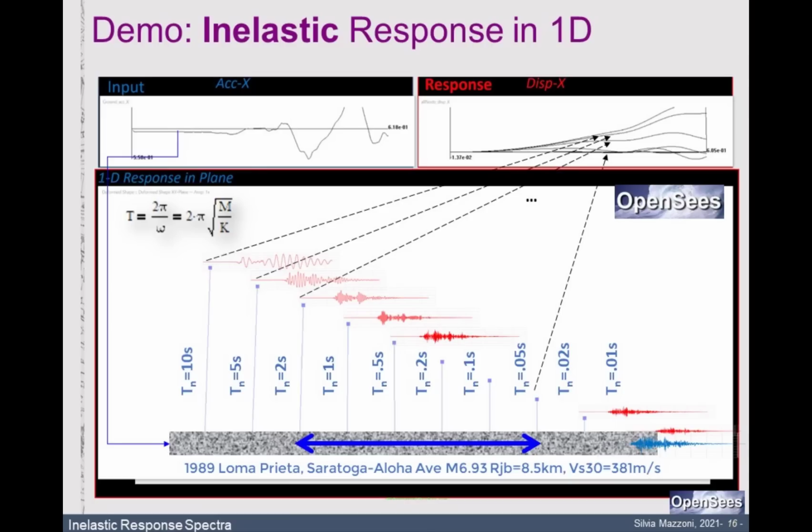And so here we have a soft story effect in this system. But really to show you, hey, look at what's going on. Not only different strengths, but also different periods will have different responses between elastic and inelastic. And another important feature, and I will address that later, is that at the end, you may end up with residual displacements. And the residual displacements are important. We are able to capture those even in a single degree of freedom system. So that, I think, is pretty cool.